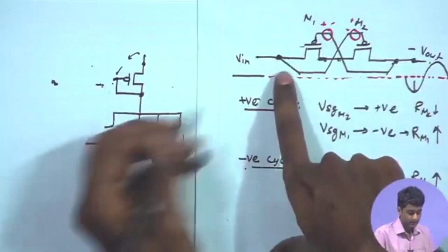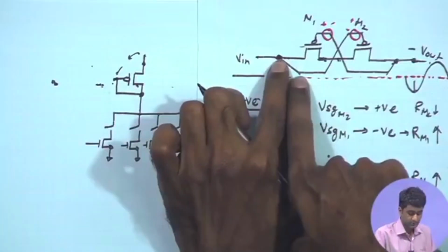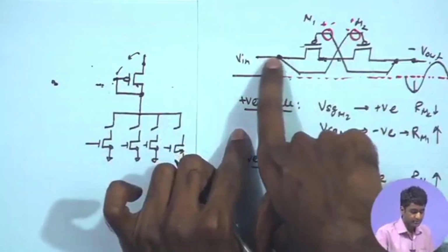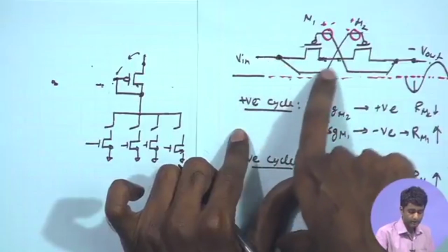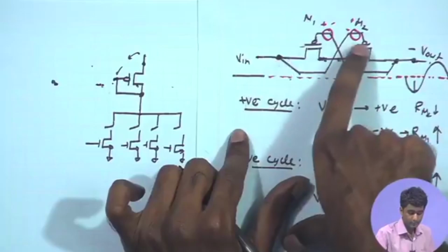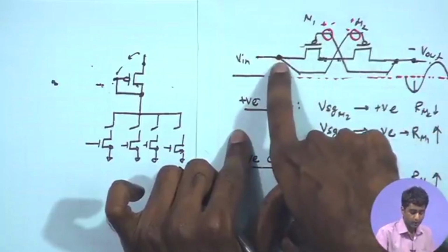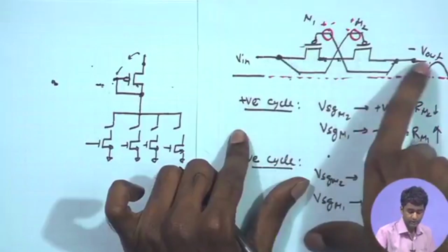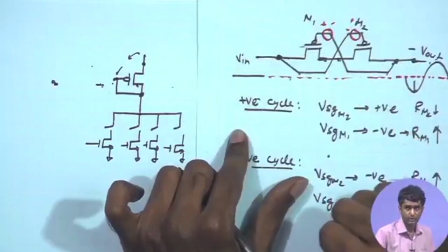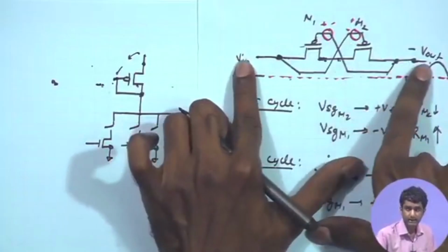We can connect the source terminal of this particular circuit at this point, and the gate of this PMOS can be connected to the gate of M2. So, that as compared to the input point, we are having an effective potential drop between the input and the gate. So, that the potentials arriving at the gate are slightly lower as compared to the potential at the input and the output point. That will basically help us in shifting the resistance towards lower values, because the effective gate potential will be lowered as compared to what we have at the V in and V out.